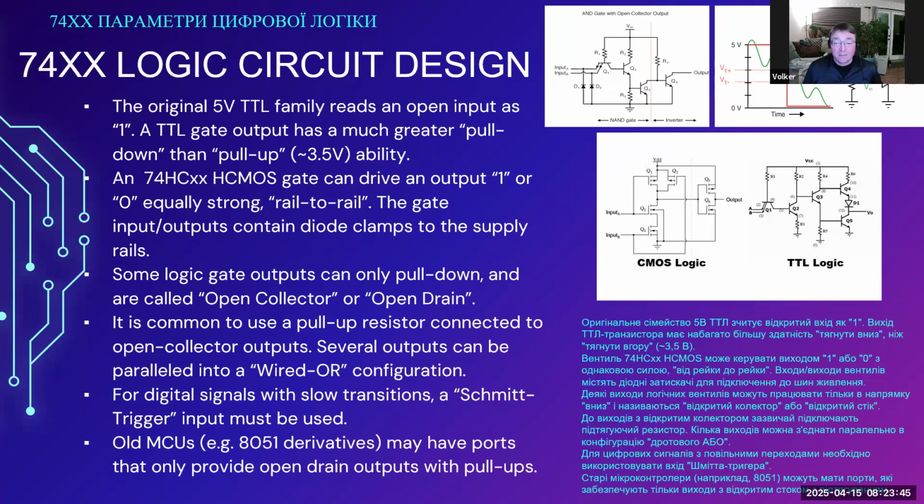And they can only pull to ground with significant strength, and they have essentially weak pull-up resistors to pull the signal up to one state. That is, if you're using an 8051 for digital circuitry, that might be something to consider.